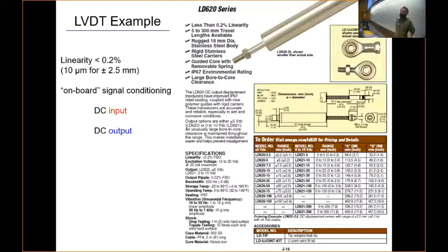Here we have a cut sheet for an LVDT. So this is a DC LVDT. Pointed out a little bit of linearity error, a pretty small amount. So FSO, less than 0.2% of the full scale output. That might be one of the most important things on here.